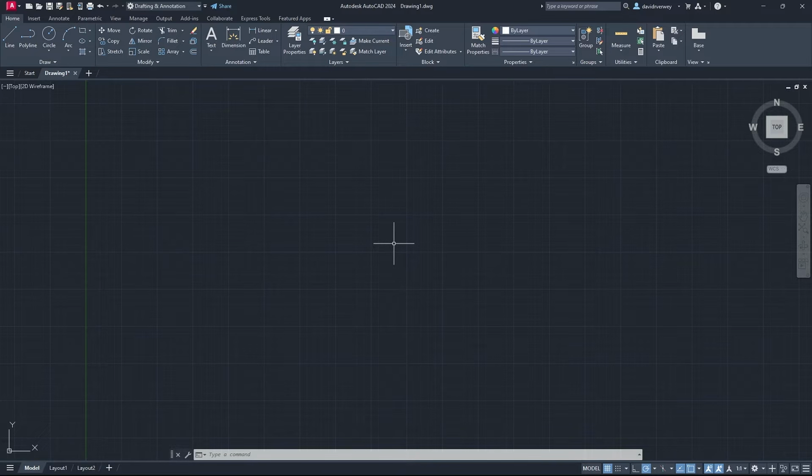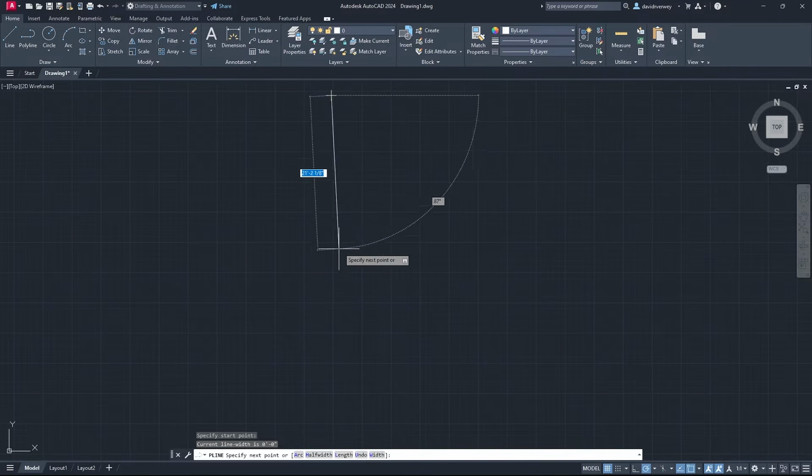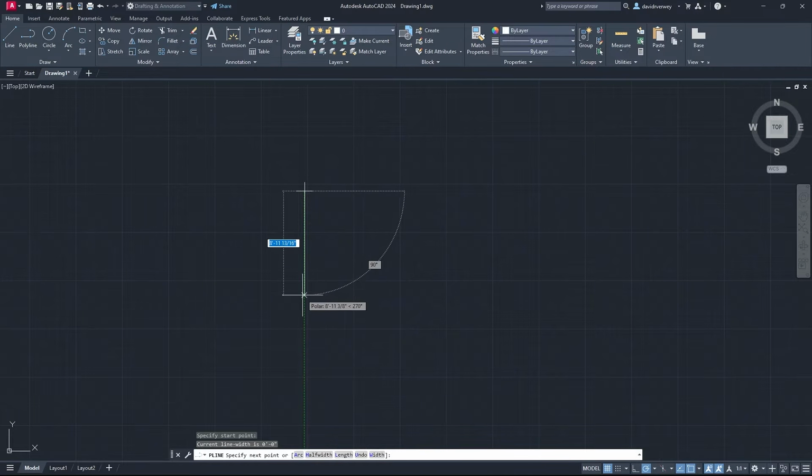We're going to be making a couch so we can insert it into the drawing that I gave you last time, and I'm going to show you how to do that. Our couch is going to be about 10 feet long. So we'll come in here and make it 10 feet, and we're going to draw it out maybe 4 feet.